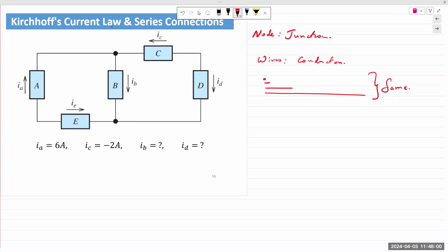The level of resistance or inductance or capacitance does not rise to the level of interference. A 100-foot extension cable might have a resistance of 1 or 2 ohms, but it does not interfere with the functioning of that cable. The purpose of the cable is to transfer 120 volts from one end to 100 feet away.